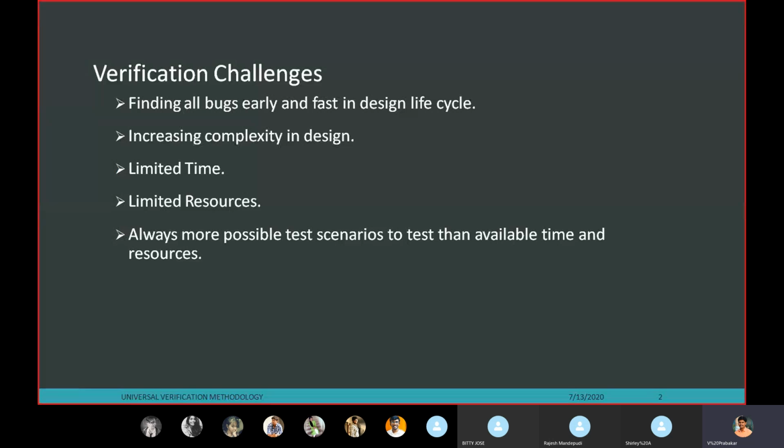here we can't reuse a system-developed testbench if we are not able to take that and reuse it in an efficient way. And also we have to write our own methods for implementing some functions, everything. If you want to do a comparison, we have to write our own compare function. But in UVM, we have all the methods inbuilt.